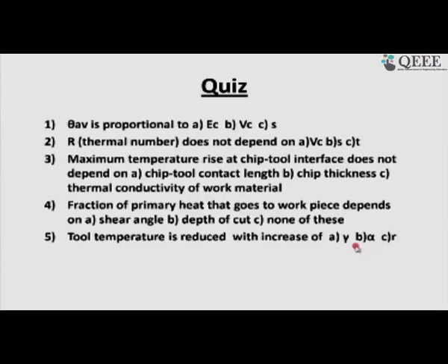But when you increase this too much, then force will rise, and if you have less mass, then you cannot have reduction in temperature. So, to add mass you have to increase the value of R. With this we have considered the cutting tool temperature issue and its dependence on this, and that is all about our lecture.